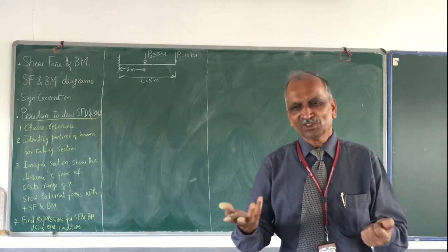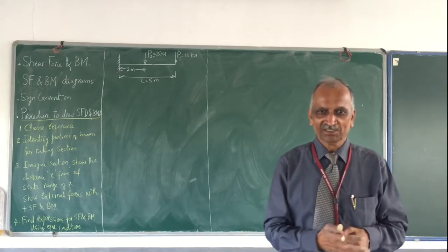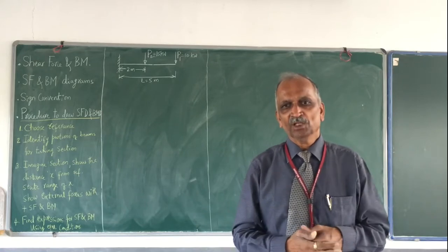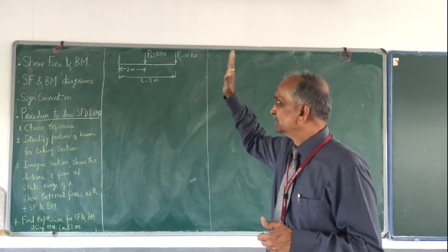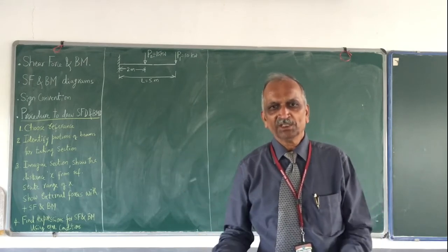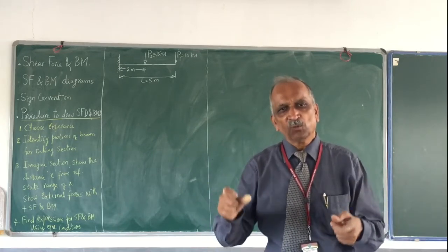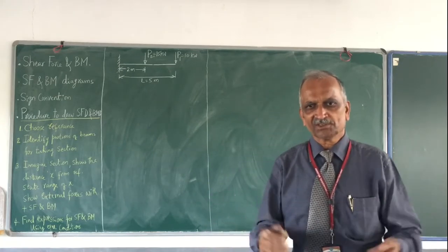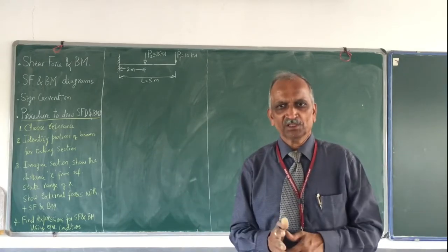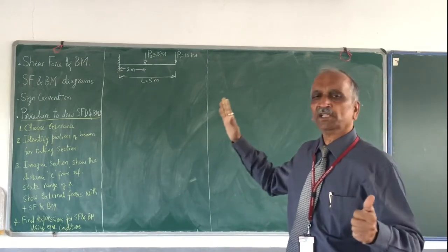Why find out this shear force and bending moment? You may have to have some more patience, you will understand. These are the ones which induce the stresses in the members. If you know at any section of the beam how much is the shear force and how much is the bending moment, we can easily calculate how much is the stress at any point and what type of stress. Is it tensile stress, compressive stress, or shear stress? All that we can find out. Therefore, we need to know the shear force and bending moment at every section.